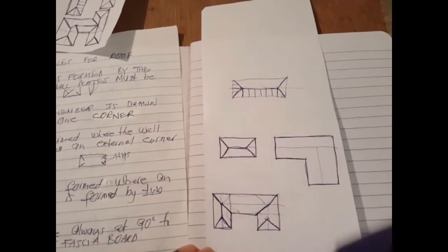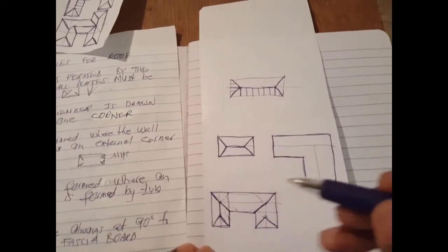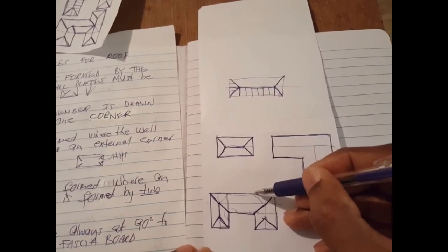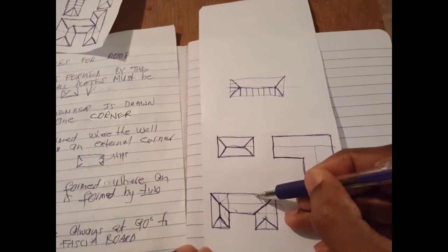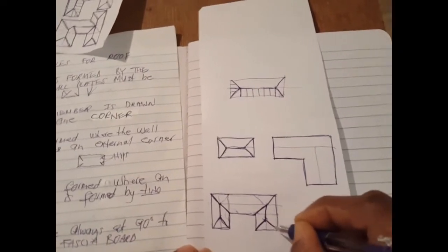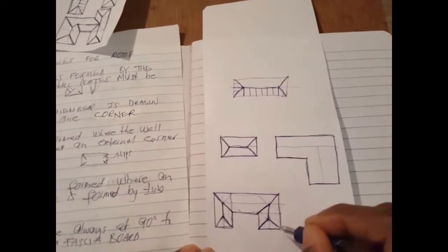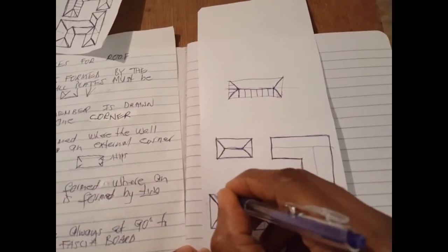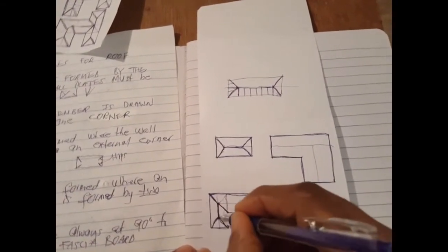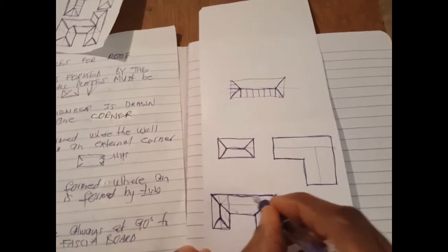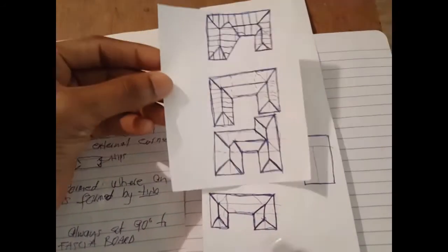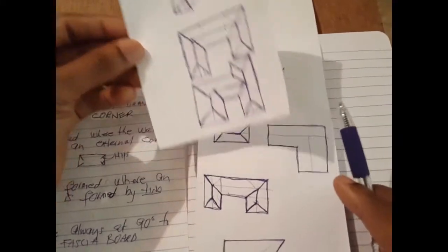All right. Now, one other important principle is that any line that is not generated from a corner must be eliminated, erased or removed. Here is our ridge line. This comes from here. That comes from that point. We draw this here, and this has not been generated from any corner, so we can ignore that one. This is pretty much the outline for the roof, which is similar to what we have here. This is that.